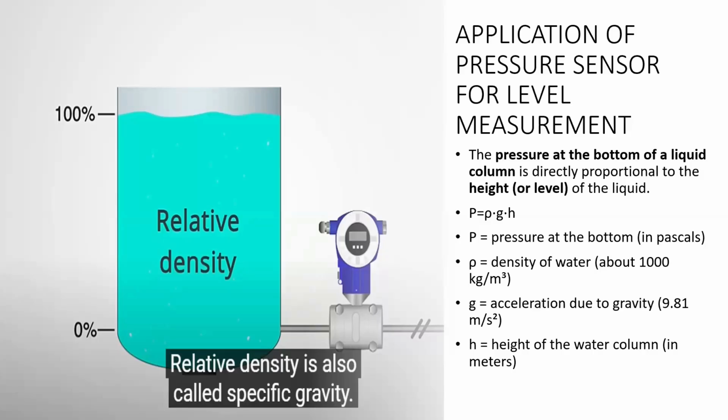To achieve a desirable result, the pressure sensor must be mounted either at the bottom of the tank or by the side, very close to the bottom. For a vented tank, gauge pressure sensors are used, like in the case of tunnel pasteurizers and bottle washers, which I mentioned earlier, whereas absolute or differential pressure sensors are used for a closed pressurized tank.